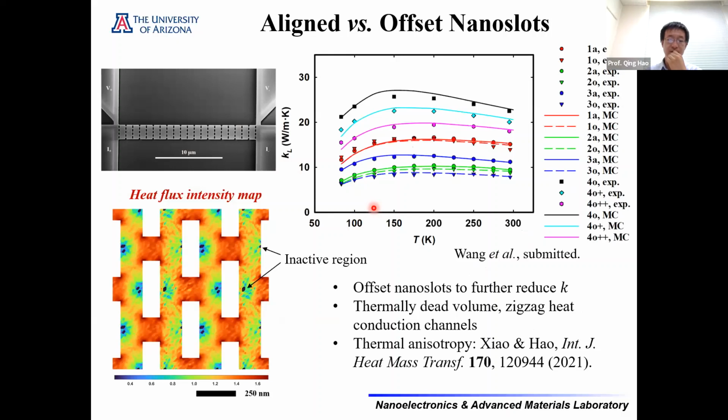This is actually our measured nanoslot pattern. We do the same, right? Of course, if you think about an ideal nanoslot, you think about 5 or 10 nanometers, which is hard to fabricate on the thin film. But this is the pattern we actually fabricated, and we do the simulation. Usually, if your nanoslot has a certain depth and you add this additional nanowire region, it adds some thermal resistance. So basically, heat has to pass this nanowire region first, and then go to another part of the structure. Adding those nanowire regions doesn't change the major heat transfer in the rest of the regions. So I'm not sure whether I answered the question.